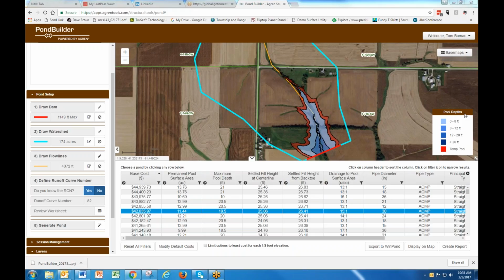The last tool that's not engineering and structural is our soil calculator. Our soil calculator calculates erosion on 3 meter by 3 meter pixels, and it uses the RUSLE II model. In 160 acres it runs about 80,000 times. What's really nice is it gives the farmer or the landowner an image of where erosion is occurring and how much. Instead of just running an erosion model one time in a field, we're running it on a raster basis and using the LiDAR data to measure slope length and steepness. Again, we're running full runs of RUSLE II, I think 80,000 times.